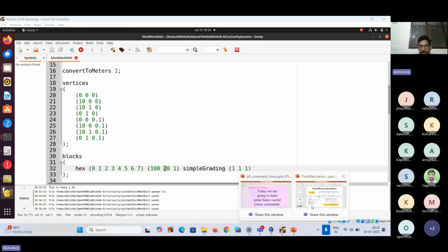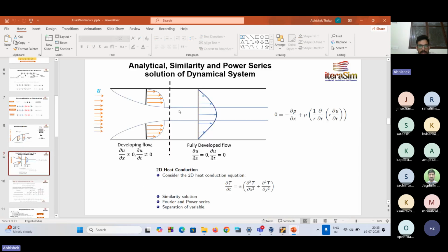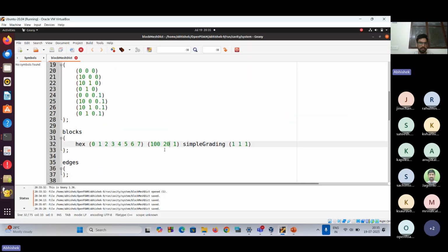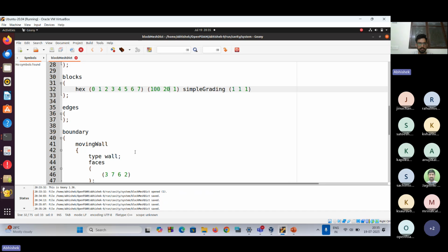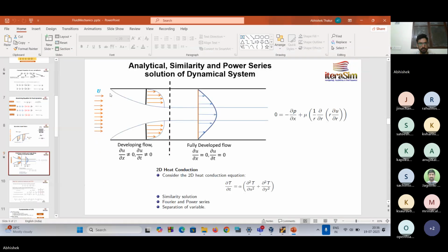So as I told here, in this particular case, this boundary layer needs to be resolved because most of the gradients are in this boundary layer. Here we don't have gradient, it's just flat. It's just bulk region, the velocity is not changing. The velocity is changing in this region. So we are giving a bit larger number of spacing in y direction. Okay. This is done.